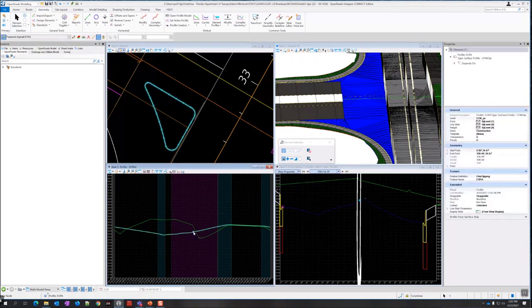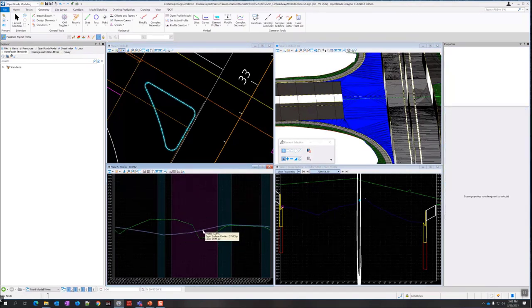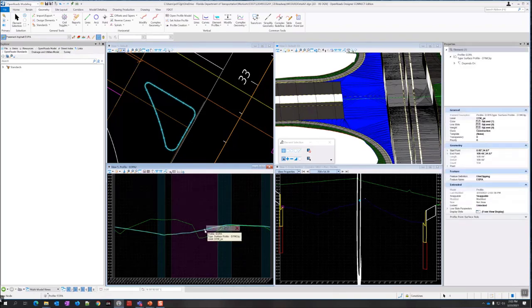Now I didn't actually use my feature definition. It pulled it from the surface. So it's just really dark blue, hard to see. But it is there. And now it's not active. So let me just set a feature definition. I don't want to use that feature definition. It's not really a good one for a profile. So I'm going to say use active and data point here.